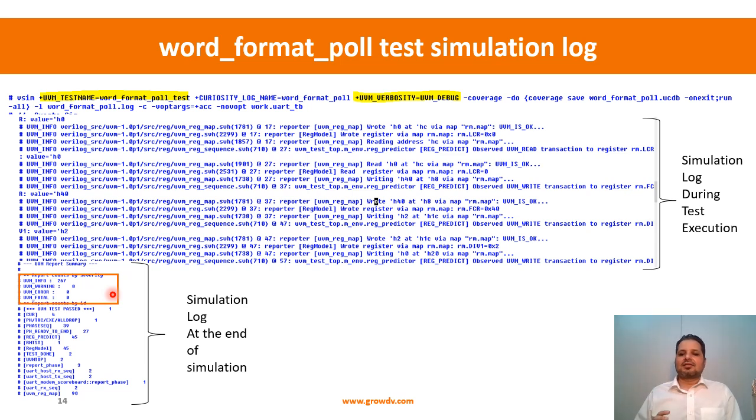and a third part, the statistics printed by UVM on the number and type of messages that have come in. At the end, even your components can provide some sort of statistics that we will look at. Before UVM prints its statistics, your test bench components can also print some statistics in the report phase. So as a part of this session, towards the end, we will see how the test and the scoreboard are going to provide some statistics information.